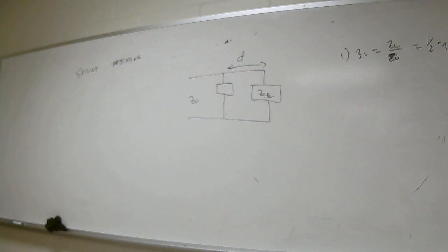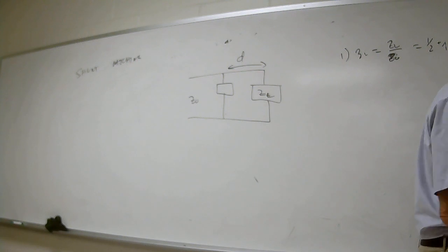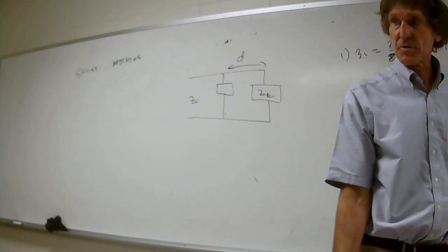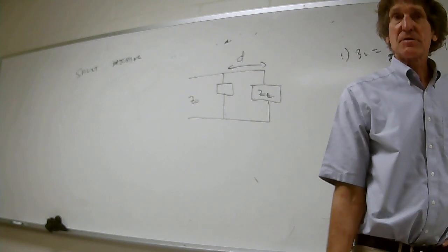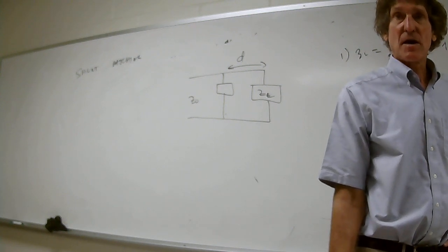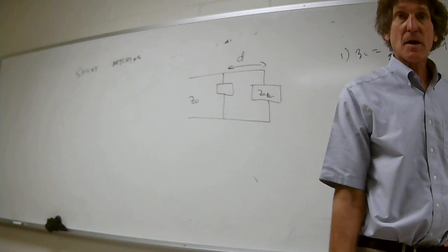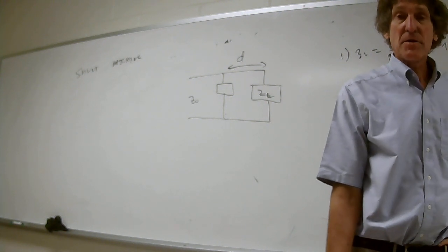Now take your straight edge and draw a line right from the center, right through here, like so. Just right through the whole Smith chart, top through bottom. It has to be from the point where ZL is through Z naught. Everybody with me? Go ahead and do it.